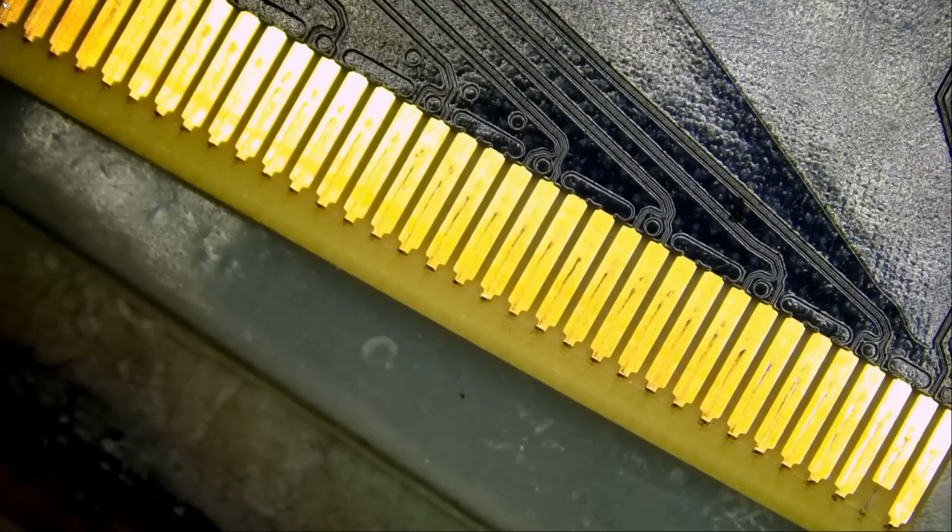All right. Visual inspection passed. Diode mode passed. Ohms mode measurements passed. Now we're going to plug in the cord and we're going to measure it in voltage mode. Okay, so we did get a chirp. Black screen, but we did hear that chirp. 1 beep and then 3 beeps.